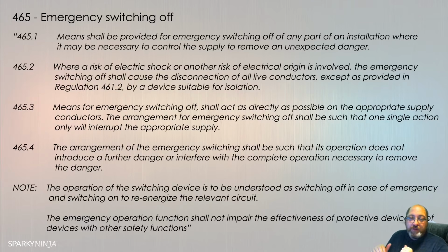method to comply. So we've talked about what these types of switching are. Isolation, emergency control, and switching are the examples given here. And if I was to say to myself, right, I'm going to use a semiconductor, can I use a semiconductor for isolation? So I'm going to go down the device lists till I find semiconductors, and I find them there, third from the bottom on that page, device with semiconductors, and it actually says no across the board for isolation and emergency switching.